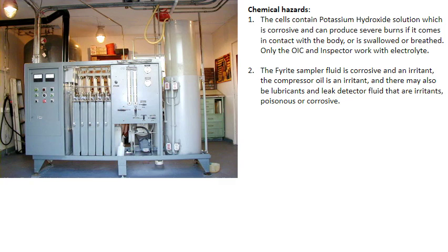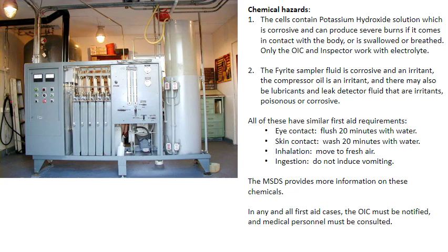The Fyrite sampler fluid is corrosive and an irritant. The compressor oil is an irritant, and there may also be lubricants and leak detector fluid that are irritants, poisonous, or corrosive. All of these have similar first aid requirements.